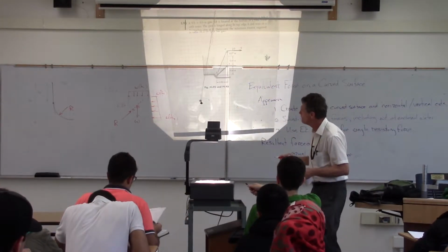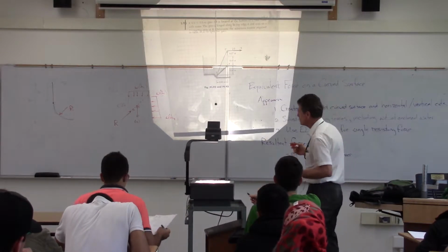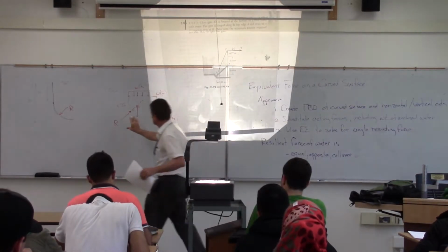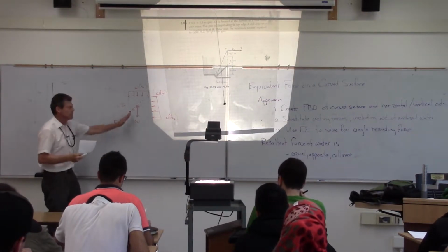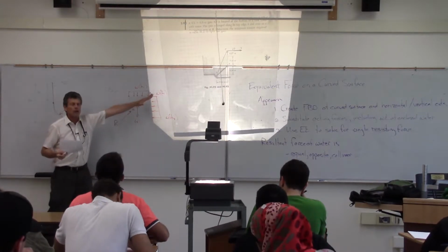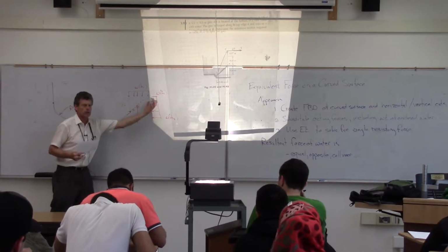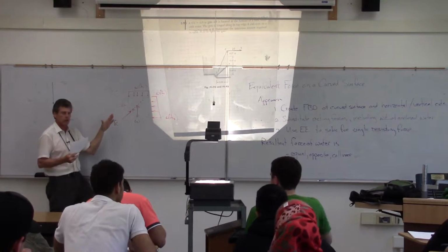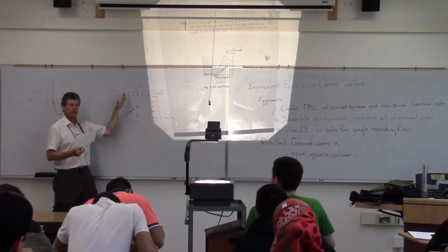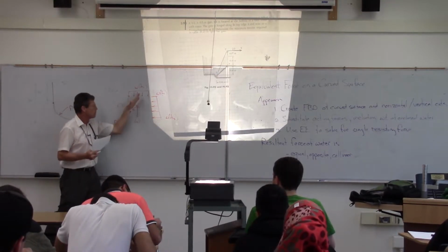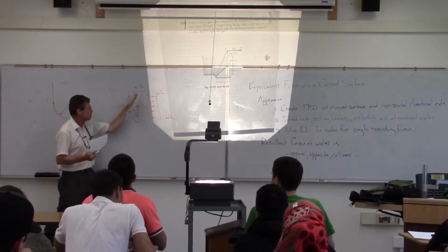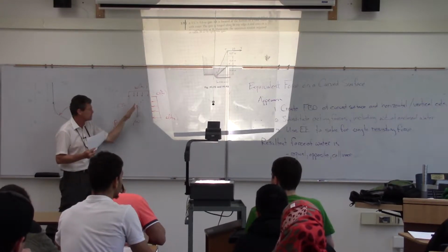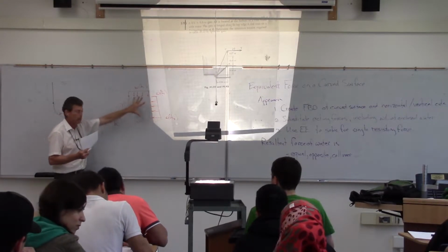The resultant is from the water force on the gate, is that what it is? Yeah, so what we did is we solved for the force that basically resists all of this, right? Because this one's pushing down, this one's pushing over, this is pushing down. So I'm going to have a force going up. When we resolve it to that single force, that's the single force that's going to keep all of that in equilibrium.